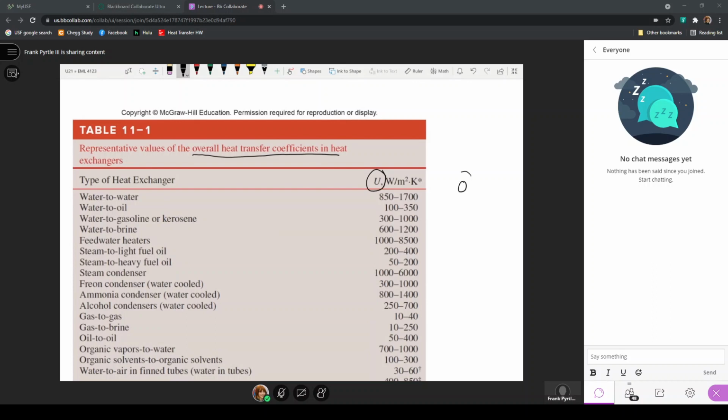Let's consider the simplest configuration, which is the double pipe. When the hot fluid is moving through the heat exchanger, the higher the flow rate, the closer we can transition. We can have a laminar flow condition, or we can have a turbulent flow condition, on the inside pipe or even the outside pipe.